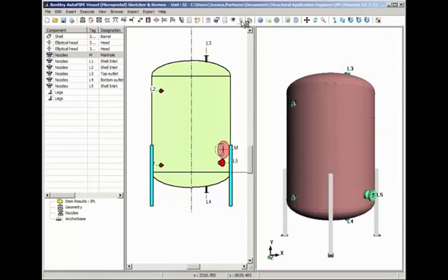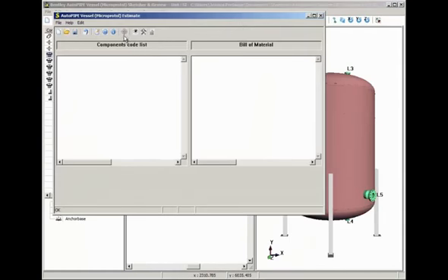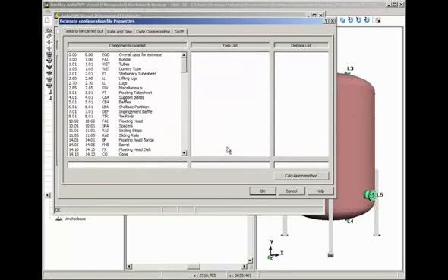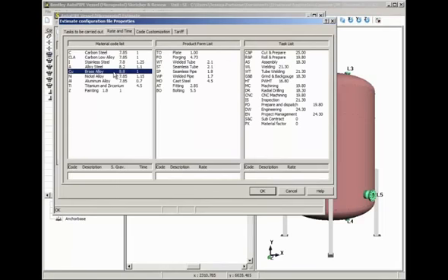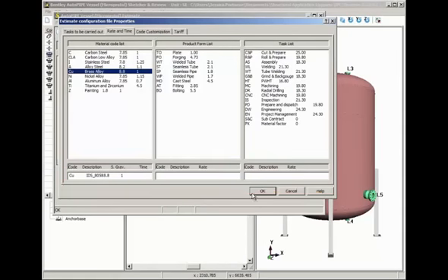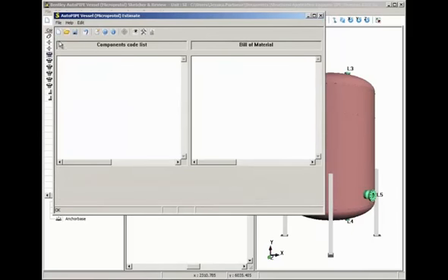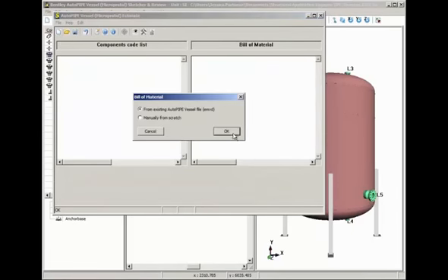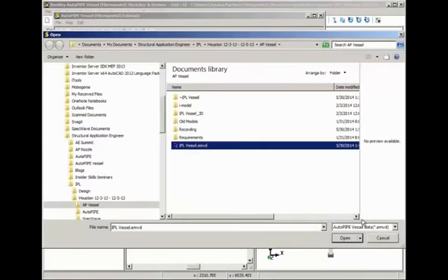So I can open up the Estimate dialog box, and I can click on the Customizable File Management, which gives me a list of components and materials. On the Rate and Time tab, I can double-click on each item to modify the rate and the time associated with each material, product, and task based on the current project requirements. Once I'm done, I can then generate my bill of materials for this specific project.